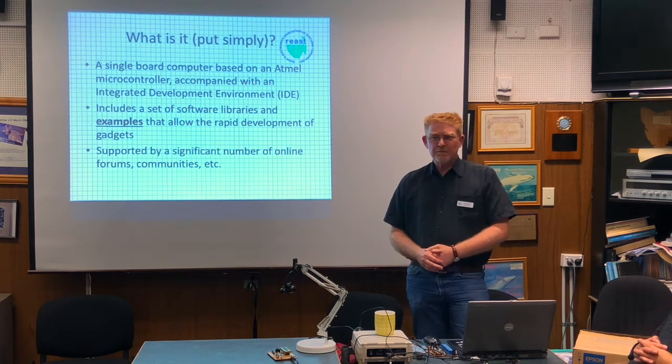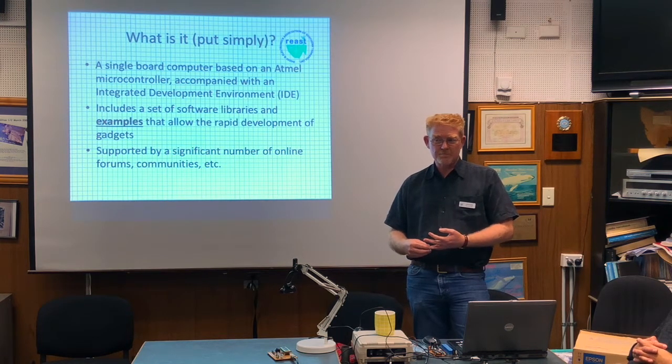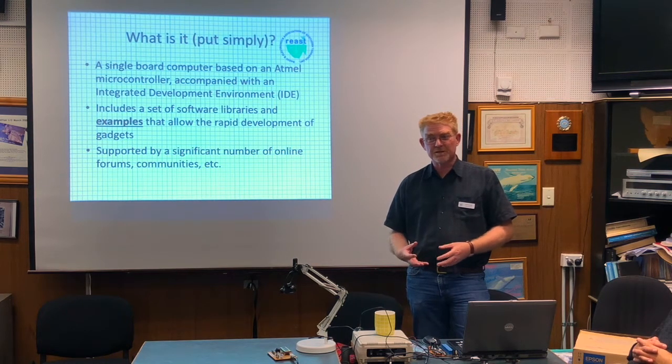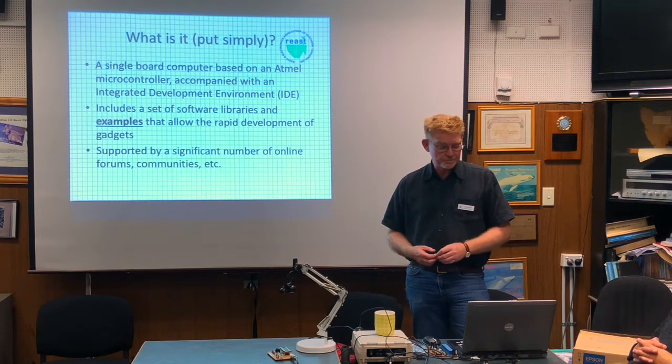The original version they put out was based around an Atmel 8-bit CPU, basically a small microcontroller with some basic peripherals: a serial port, support for I2C, SPI, and a mix of analog and digital I/O. So a range of capabilities to either talk to simple sensors or more complex chips as your skill set and your needs grew over time.